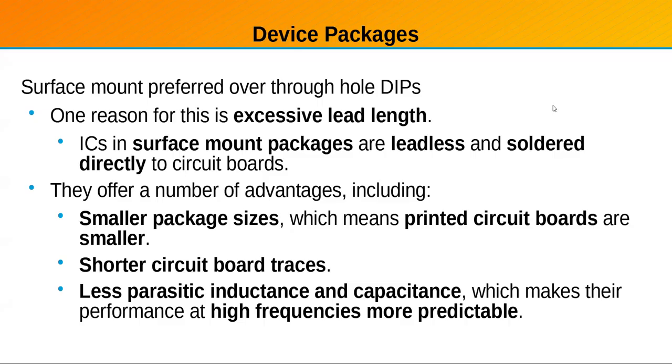But if you're old and got bad eyes, it's hard to do. Fortunately, I'm old, but I got good eyes. And you really need the right kind of tools. You can do 1206 size with a regular soldering iron, a small tip, magnifying glasses, and tweezers. Otherwise, it's easy to lose.